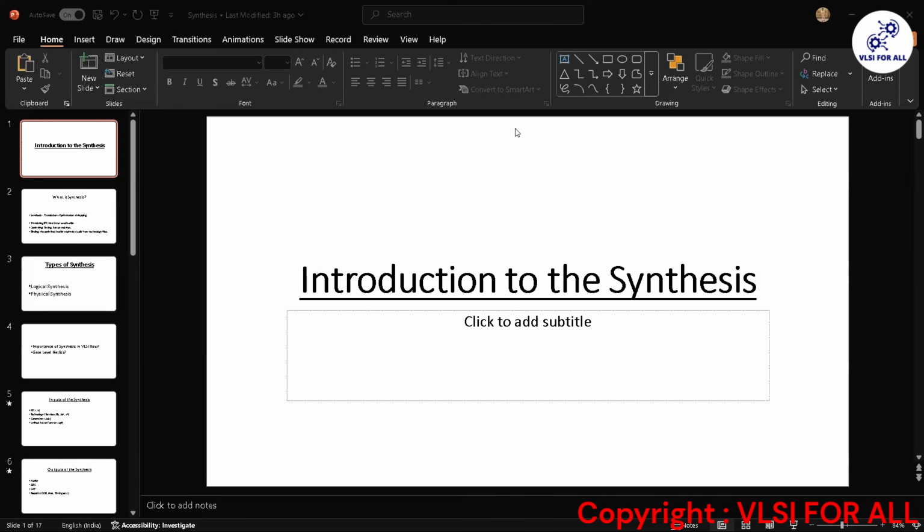Actually, these are the techniques used to generate the .lib file, that is the Liberty files. The CCS contains 20 variables, and NLDM contains only 2 variables. So CCS is 10 times more in size compared to the NLDM. But it is detailed and accurate; the disadvantage is it has more runtime. Whereas NLDM is 10 times less in size than CCS. So it is less accurate, of course, but the runtime is also less. That is the advantage. So let's see the next one.